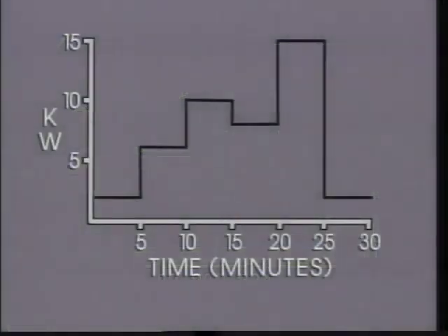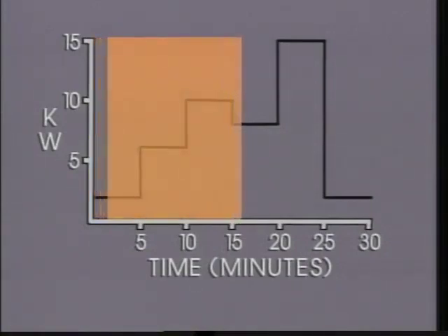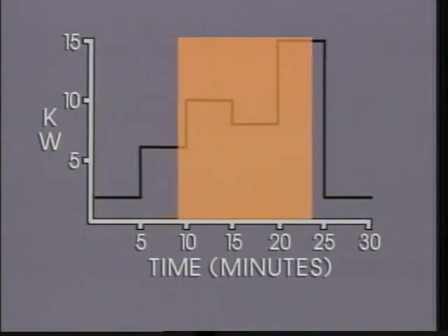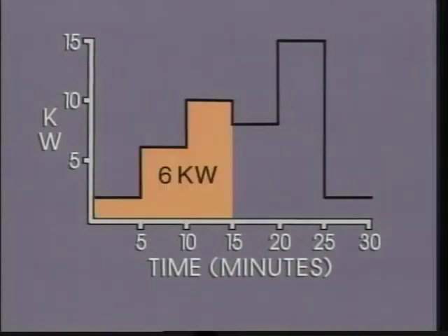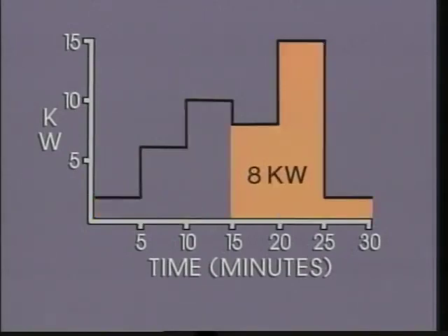With a rolling interval, the microprocessor looks for the block of time with the maximum demand. That block of time may include demand that would normally be registered in successive time intervals. For example, here, the demand for a typical fixed 15-minute time interval is 6 kilowatts. The demand for the next fixed 15-minute interval is 8 kilowatts. If a rolling demand interval is used, the block defined from 10 minutes in interval 1 to 25 minutes in interval 2 shows a demand of 11 kilowatts. Rolling demand overcomes the user's ability to split large loads between two intervals and effectively lower the indicated demand.